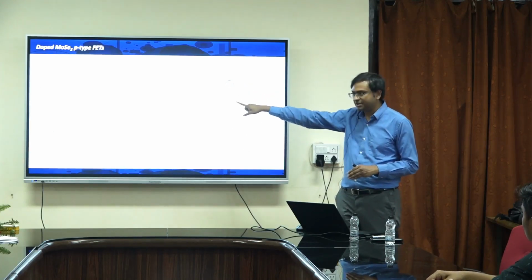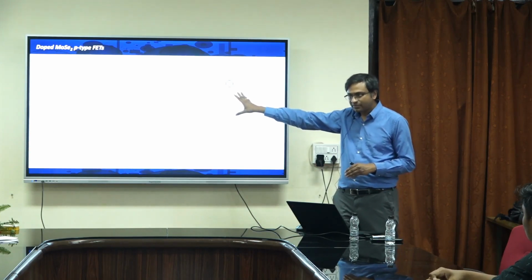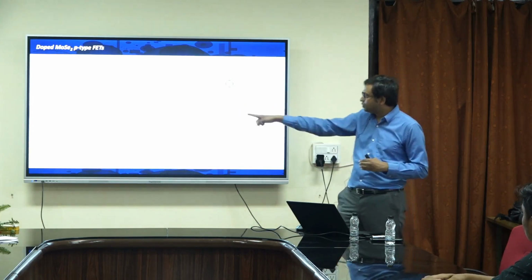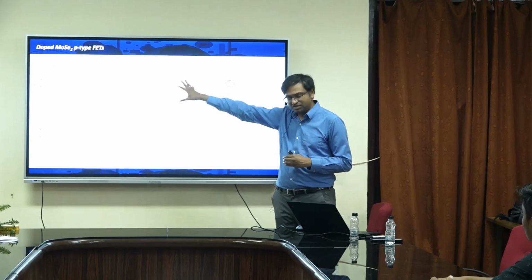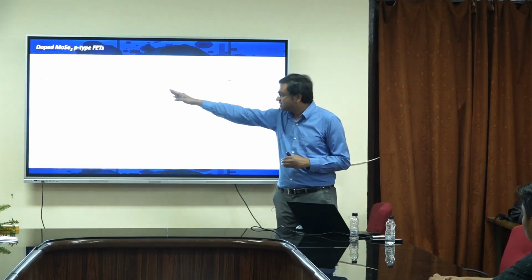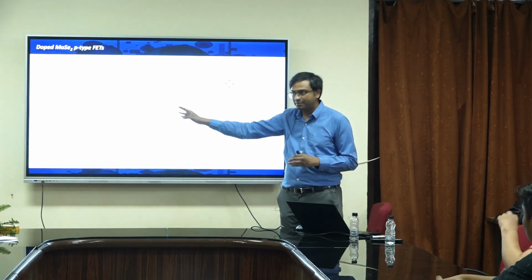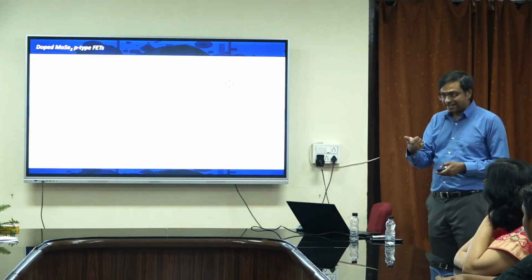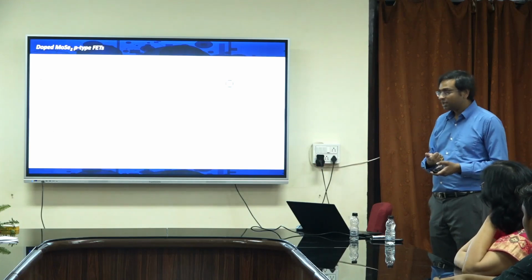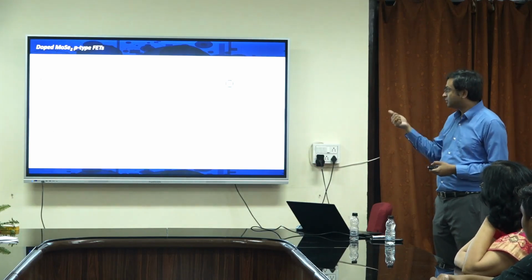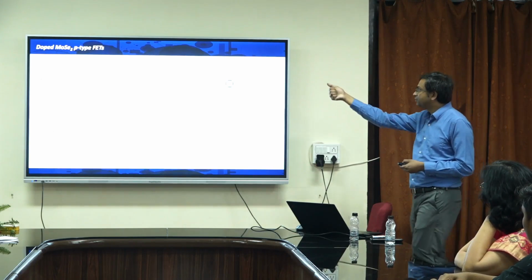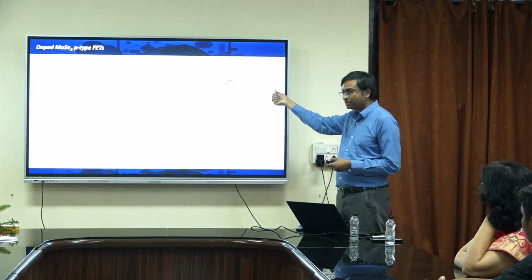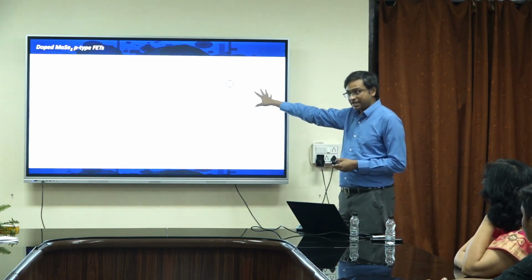And you can see that the pristine material is already a little bit P, right? Because the Fermi level is mid gap, but you also see the pristine material is N, but there is a little bit of P branch, which is not there for MoS2. Okay? So pristine material is N type, but once I dope it, something quite interesting happens. You see that with niobium doping, tantalum doping, and vanadium doping, these are now P type.